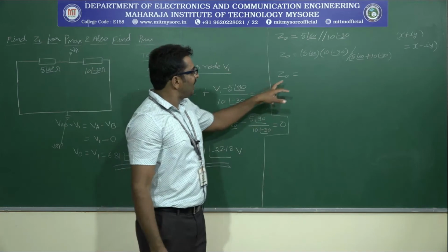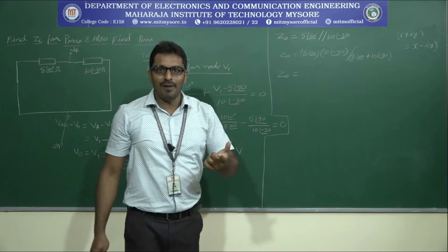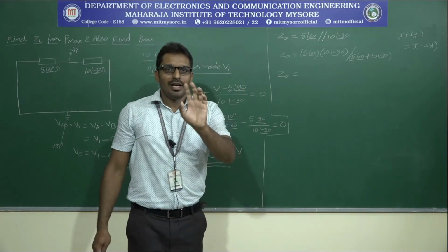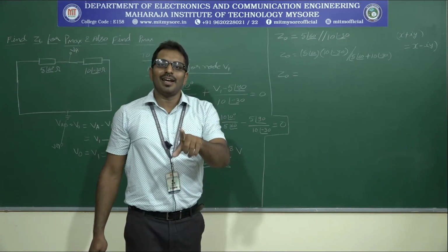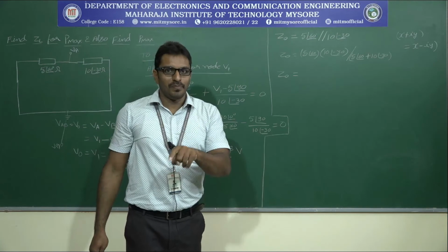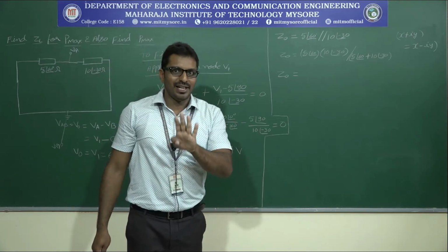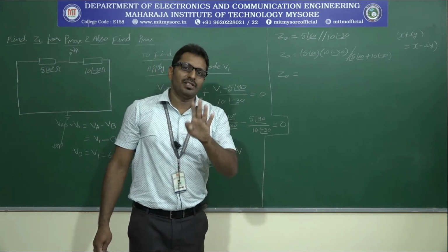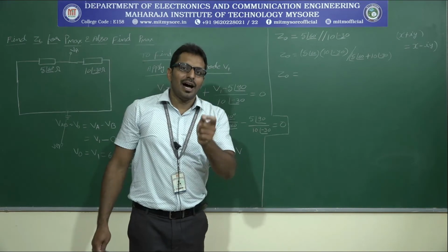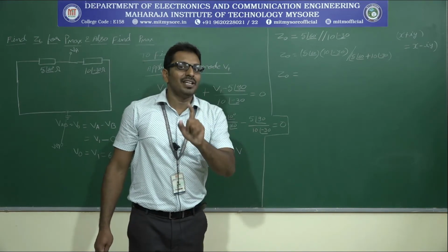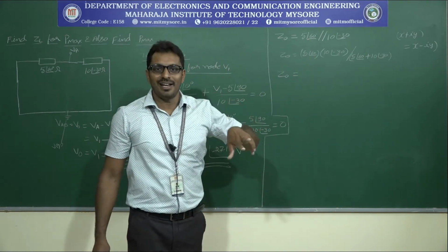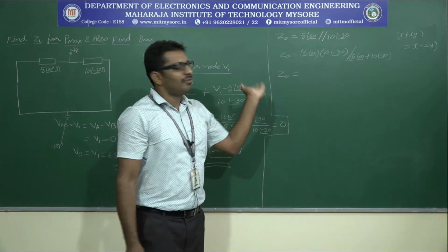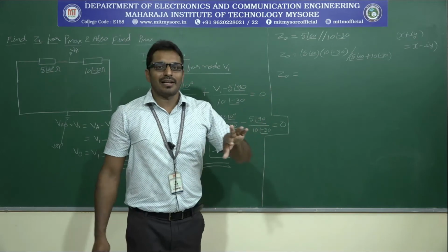Anyhow, first I will write what the Z0 value is in polar form. Again, you have an option to take the answer in rectangular form, right? Shift 2. Then you will get 4 options, right? Out of those 4 options, one is r at an angle theta. Another one is a plus bi. A plus bi form is nothing but rectangular form. Please try to convert polar form back into rectangular form.